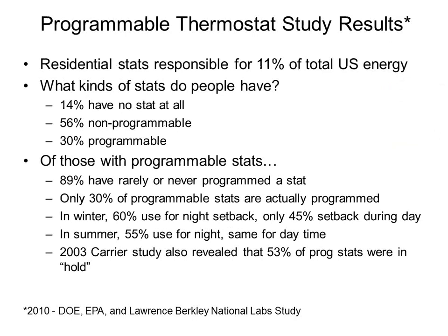Jonathan asks if ASHRAE and energy codes establish required setback temperatures and differences. And yes, there are some of those. It's different depending on the type of scenario, but there are some rules on what you have to do initially when you set it up. But there's nothing that makes the building occupants keep using those, so I don't really pay attention to that much. The guy setting up the system has to plug in these setback temperatures, but there's nothing that makes the building owner use it that way. So that's a good question, Jonathan.